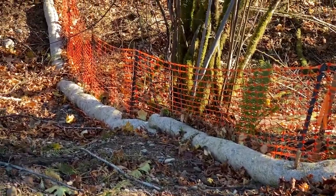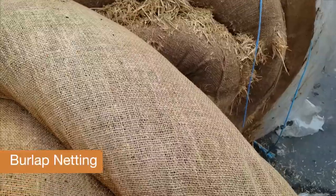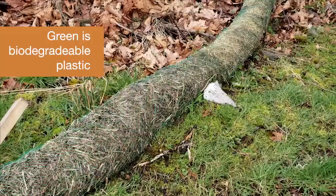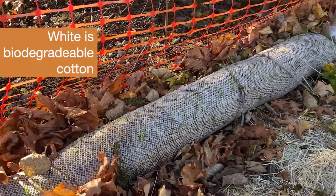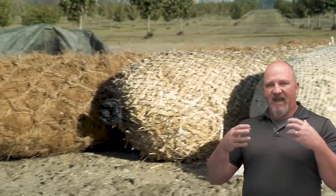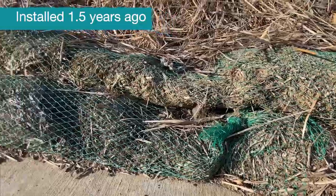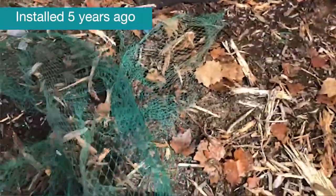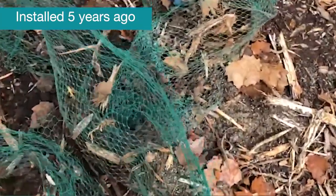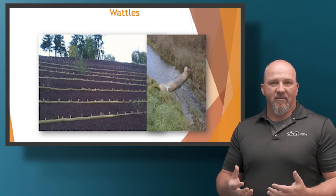What's important about your wattle selection is understanding what type of netting is on the outside. Some can be burlap, some can be green netting, some can be black netting, some can be white netting. They all have different longevity to them. The nettings have different biodegradable timelines to them. You might need to go back on some projects and pull the netting back out because they don't break down in time. So really making decisions about what wattle you're going to utilize has a lot to do with how long you want it to last and whether you're going to walk away from it and leave it on the site.